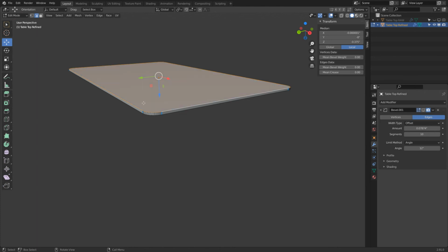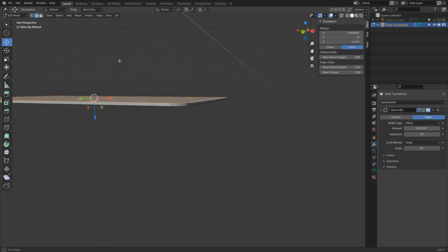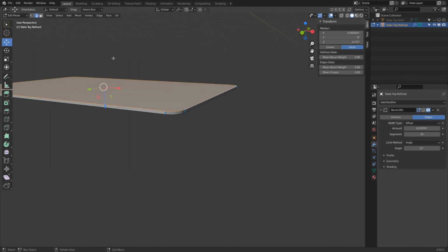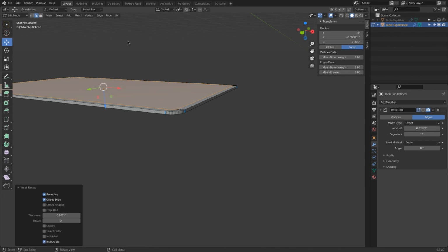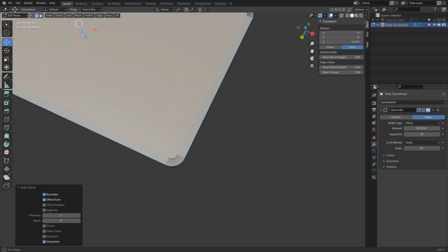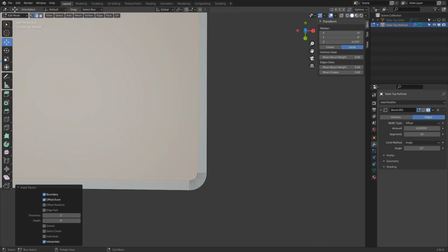There. Very good. Okay. Now we have a nice flat disk. And what we will do now is we will go back and say inset face by 1 inch. There we are. Very nice. Now, there you see now how this is actually smaller. This is correct.